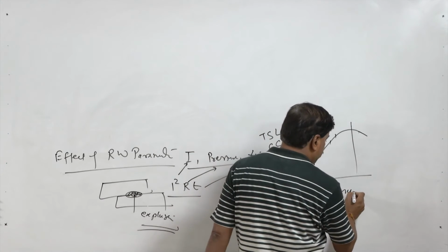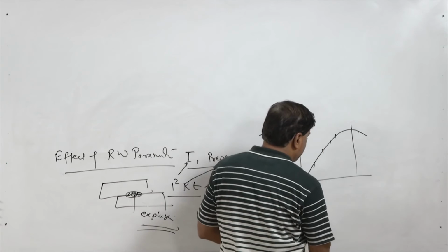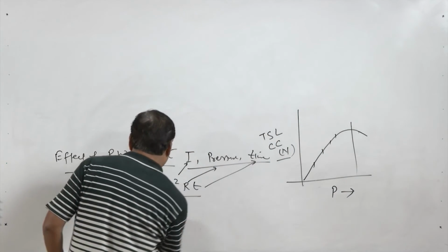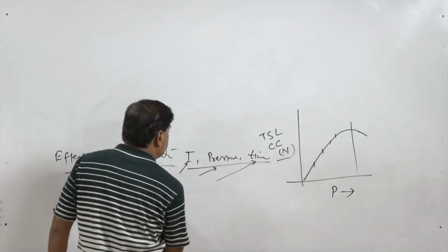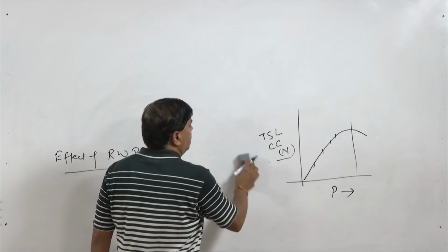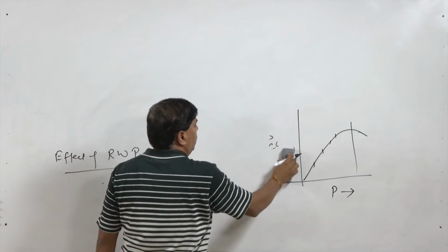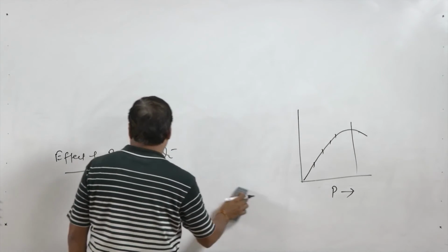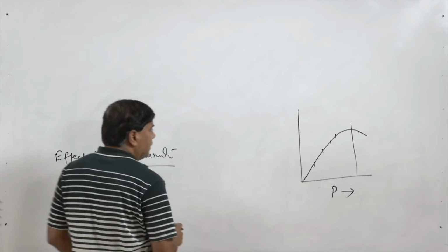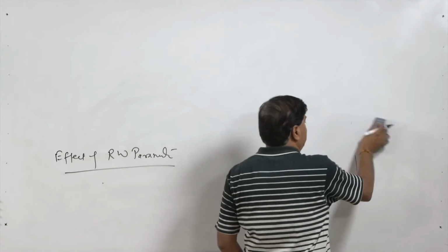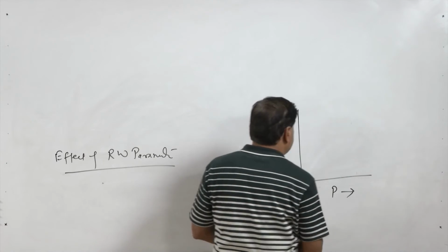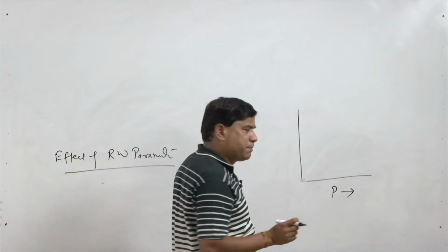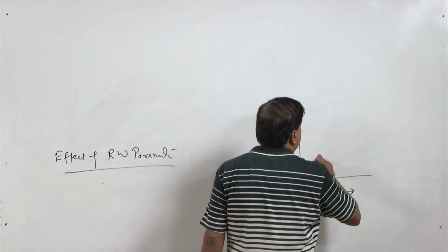So, with the increase in pressure or the load, of course we need some minimum contact pressure in order to have good current flow through the workpiece without sparking. Initially, when the pressure is less, the current will not flow without sparking, so some minimum pressure is needed.